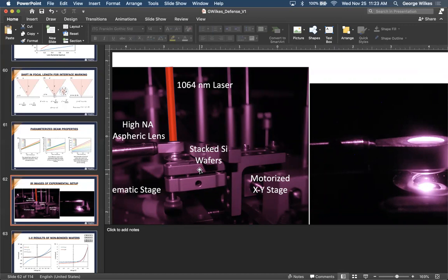One thing I'm curious about is that if you apply the water, you can minimize the gap between the two wafers, because the interfacial thickness of the oxide layer might affect the electrical junction a lot. The other question is whether this might work for other material systems. Have you ever tried to bond silicon to another material for heterogeneous integration, like gallium arsenide or other material systems?